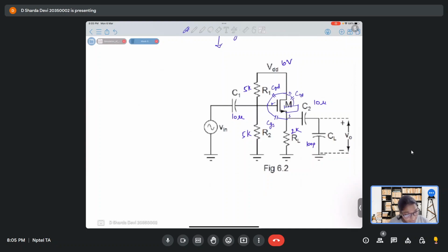So here what happens is, when we are talking about input capacitance Cin looking from the gate, here we will see that there is a capacitance which is between drain and gate. This gate and drain will actually look like gate and ground, CGD, right?